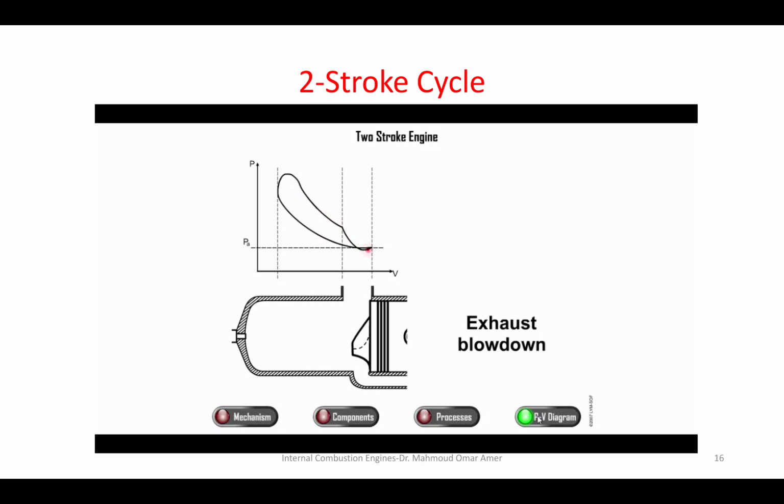And does the fresh charge displace all the exhaust to the outside? No. Part of the fresh charge mixes with the exhaust, and part of the exhaust remains inside the cylinder. And part of the fresh charge exits from the exhaust port. So the overall cycle efficiency is what? Is lower. But which engine is better?